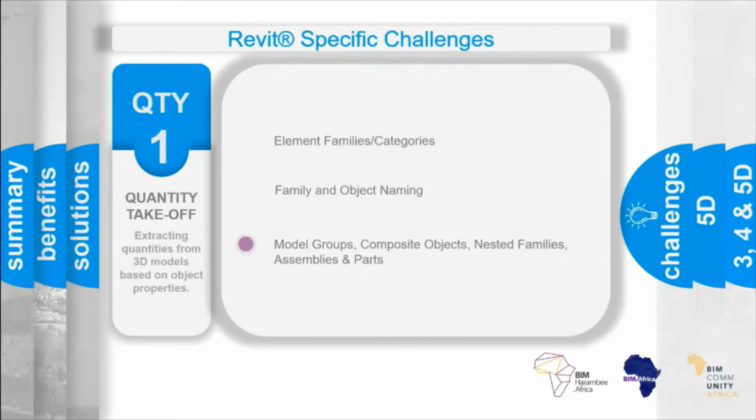So if we look at model groups, for example, model groups will allow multiple elements and objects to be locked for editing, then copied and applied multiple times in a building or in a model. Autodesk suggests that the grouping of elements is useful when a modeler needs to create entities that are repeated or are common to many building projects. So items such as repeated hotel rooms in a hotel development or apartments, or even floors that get repeated. These could be created as groups and repasted.